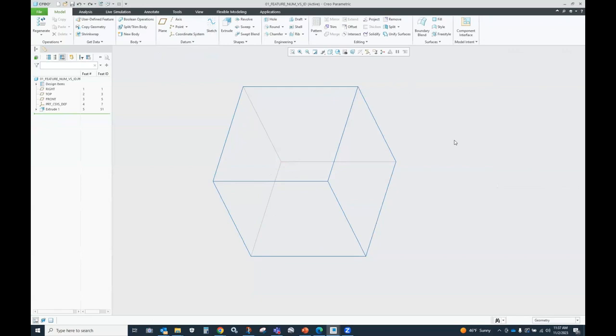Right, because I'm still using the intent selection that's built in, right? So in this case, I probably have three, there might be more, but there's three intent selections, right? There's one there in the back, right? That's ID 76. There's one in the front, which is ID 75. And then there's this one, which was ID 77. I guess my question is, how is it determining those exist? Because those are sharp edges created in that extrusion, right? So if I had extruded around on that corner, there wouldn't be any edge to pick there, right?